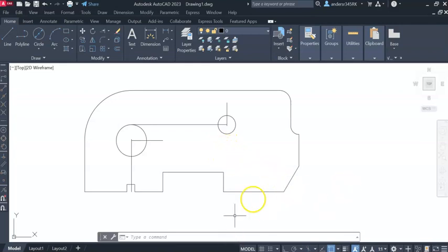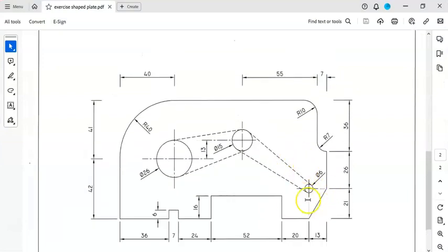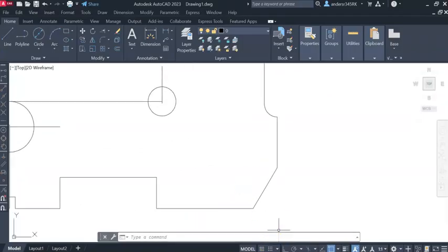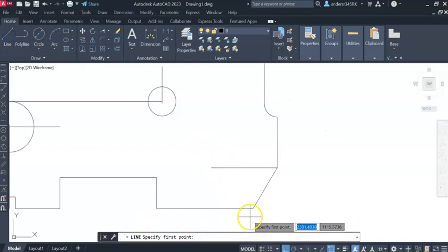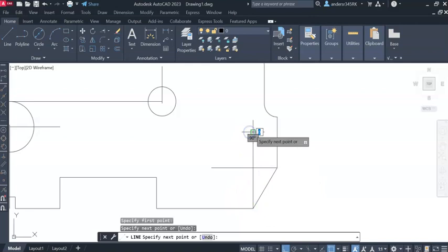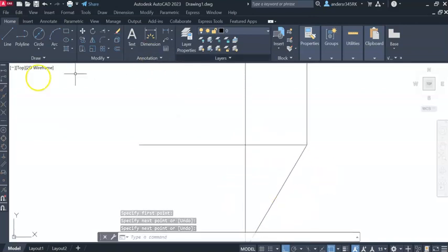Okay, I want to draw in this other circle over here. That one there. And that circle sits here. So if I take that corner and I draw it out, take this corner, draw it out, where they intersect, that will be the center of my 6 millimeter diameter circle. Right. See that auto is on? That's on there. I'm going to go to line, draw a line from there to there, pull it out. Just click anywhere there, hit enter, go to line, snap to there, pull it up anywhere there, click there, hit enter to break it off. That's the center of my 6 millimeter diameter circle.